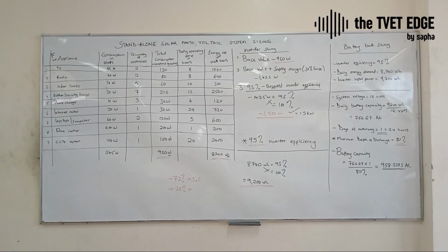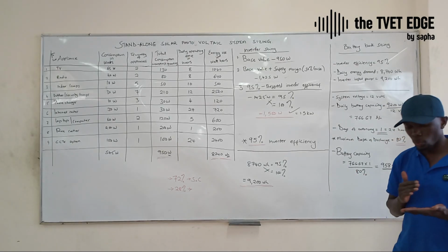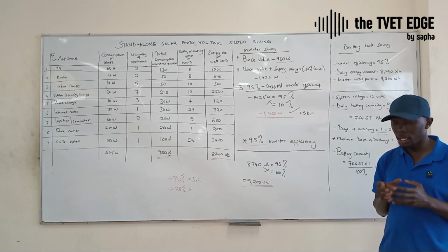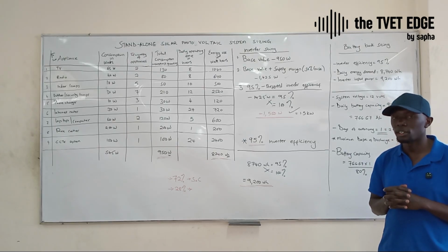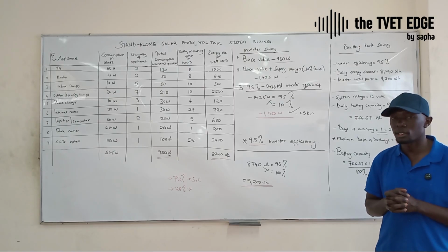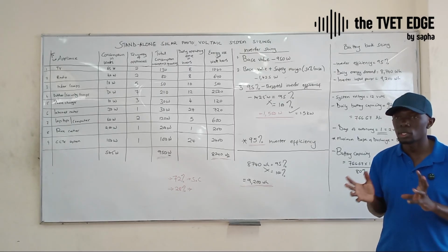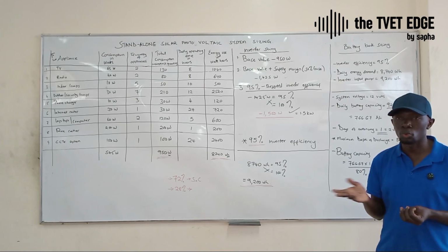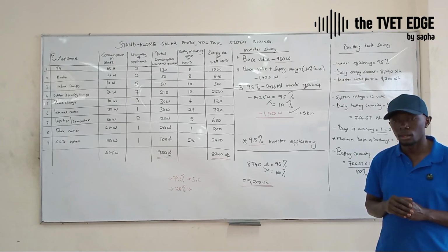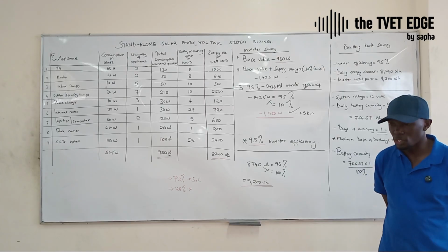In a solar system, we are always looking for not to drain the system before the next charge cycle. And I explain what a charge cycle is. When you start, like the first time your system is installed, it's very rare for that system to come at 100%. The batteries will never come at 100% state of charge. They'll come probably at around 75, 80, 85% state of charge. Some will have drained to probably up to 60%. And I explained what a state of charge is. And I explained what a charge cycle is.